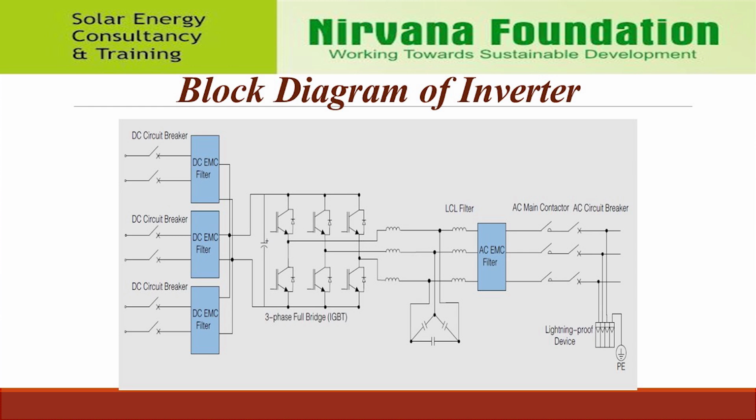Block diagram of inverter. DC EMC filter. EMC filters reduce the transfer of electromagnetic noise between the drive and mains power supply. Reduces conducted emission towards the solar panel. These DC filters in PV installations help increase solar panel reliability and immunity in the inverter control phase, avoiding any